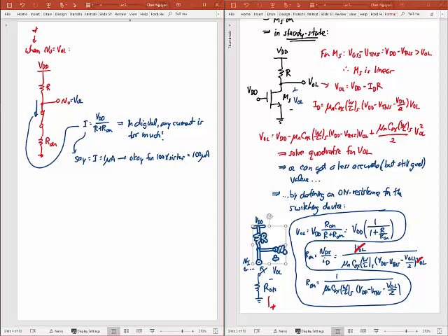Okay, but how many transistors do you have in your CPUs now? With cache and all of that, you have 1 billion transistors now, right? Multiply that by this 1 microampere. Suddenly you have 1,000 amperes. Okay? That's way too much.